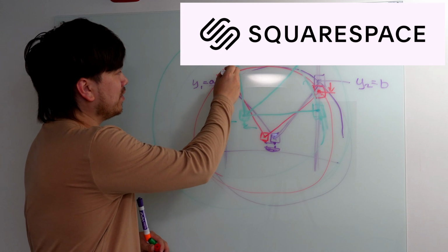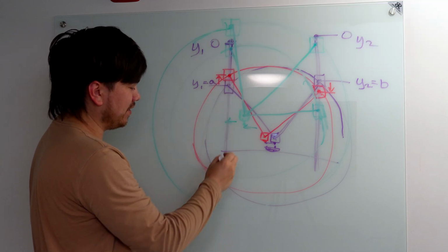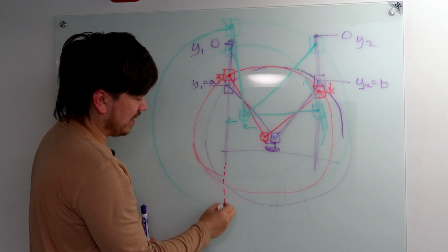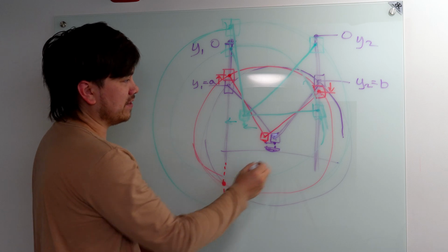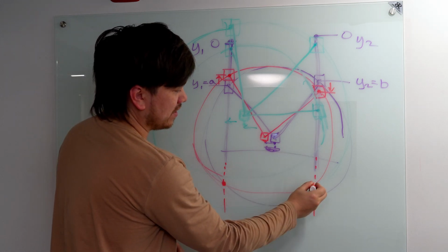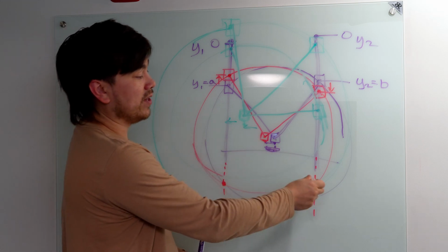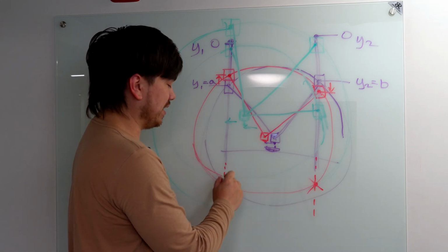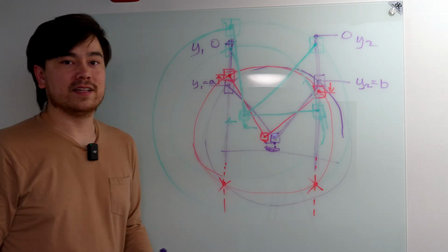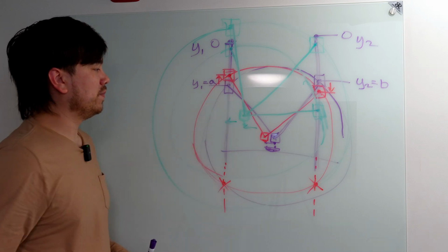Let's keep on erasing this thing. With this red example, you can see there's this intersection up here, and then if you look down here, there's actually another intersection with the circle down there. Likewise, on the other side, there's a second intersection point. So you're just gonna write some logic to ignore this bottom intersection and just assign the linkage to move to this position.